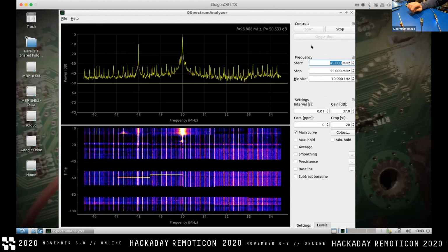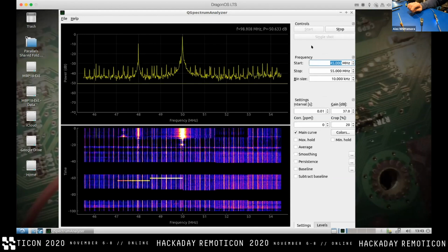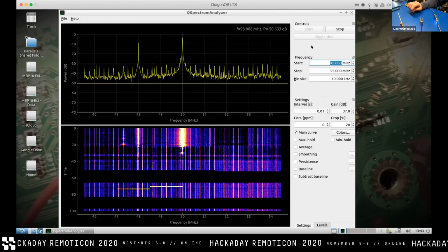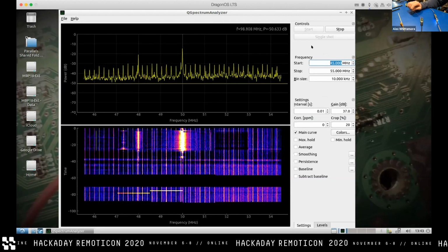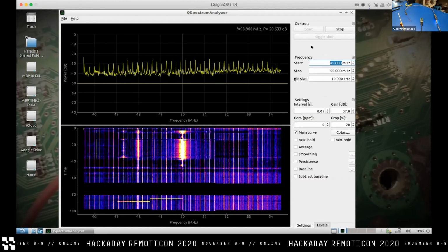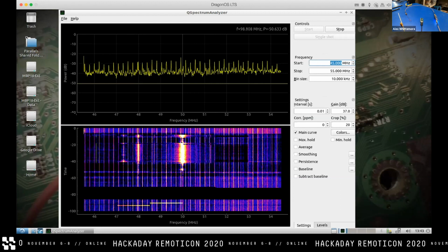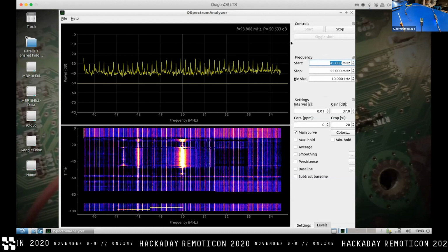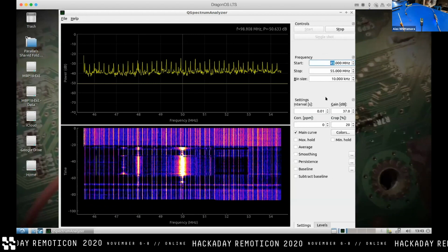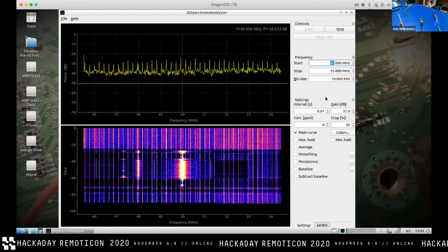What we definitely see is there is a colossal 48 megahertz peak there, and there is a colossal 50 megahertz peak there. And as we move it around, we see different things happening. So this is definitely what we're kind of looking for. And what I really like about QSpectrumAnalyzer is at this point we can just narrow in a little bit further.